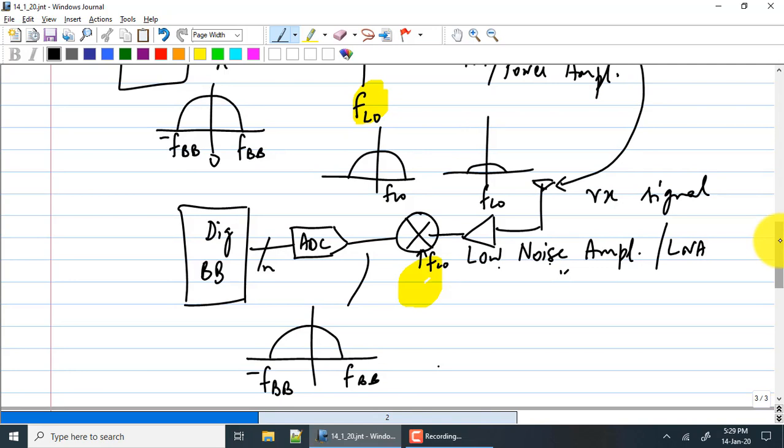I'm going to look at the receiver. Where do I start? Normally the antenna itself is not part of the integrated circuit proper. It is a separate device because the size of the antenna is normally related to the wavelength at which you are operating. Normally the wavelength for wireless communication is so large, typically in centimeters, that the antenna is too large to put on the IC. Centimeters is very large for the IC. So normally it's a separate component, which does not reside on the IC.